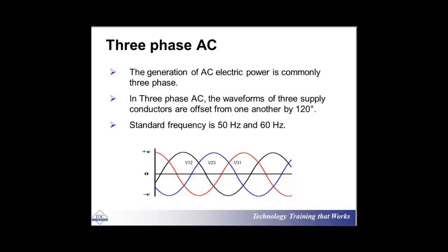So they give you phase A, they give your neighbor phase B, they give another neighbor phase C, and again A, B, C, and again A, B, C. This is how they distribute the three phases in your street. However, the important thing about this three-phase system is that you have to distribute it as equally as you can. If you don't distribute it equally, you will have an unbalanced system.